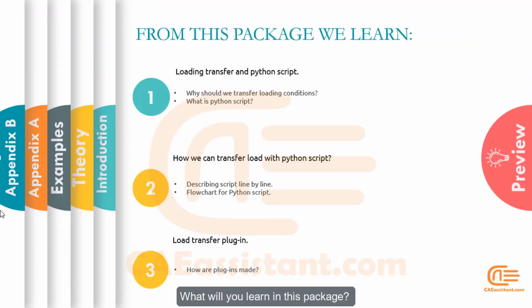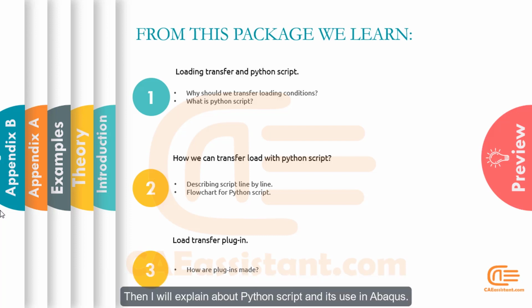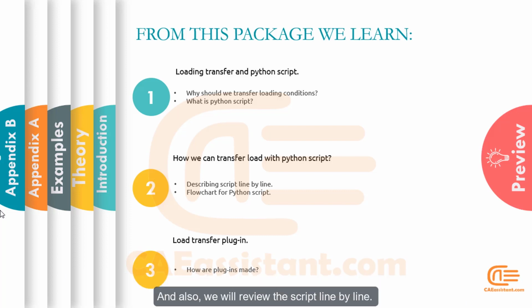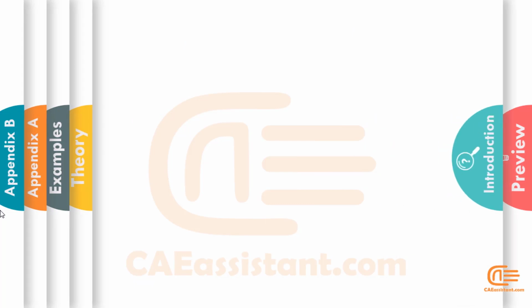What will you learn in this package? In this package, we first study the reason why we need to transfer loads from a CFD analysis to a structural model. Then I will explain about Python script and its use in Abaqus. In the next step, we will review the prerequisites for using Python script and also its flowchart. And also, we will review the script line by line. Finally, in the last step, we will learn how to create a plugin to transfer loads.